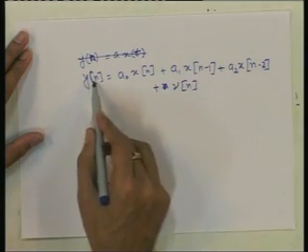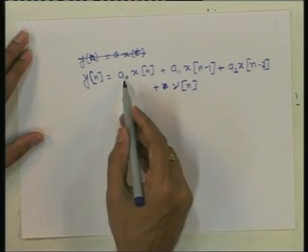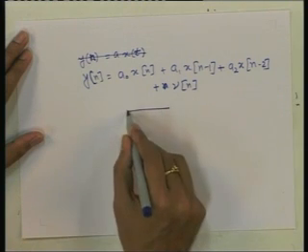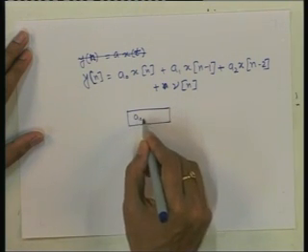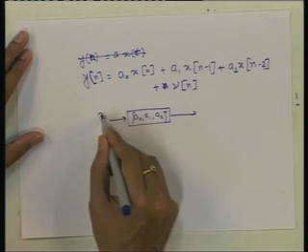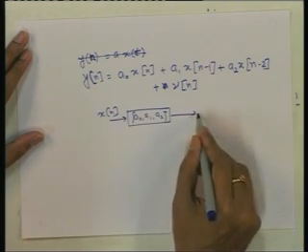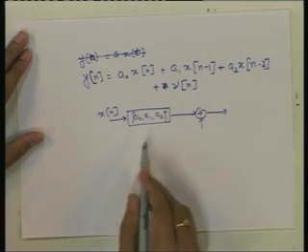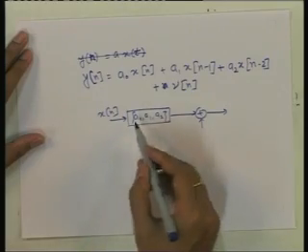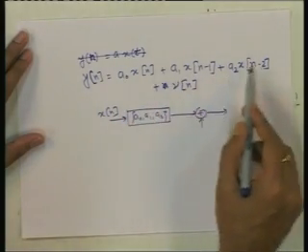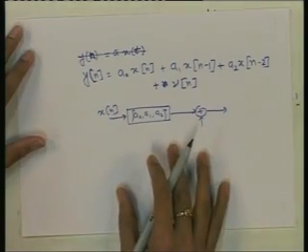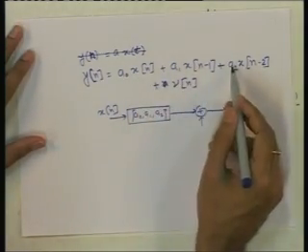Then it is like this signal is going through a filter. So, this is basically a filter with impulse response coefficients a0, a1, a2. This is the filter impulse response xn is going through. Then noise. So, multiple paths in the channel give rise to a linear filter channel here, and these filter coefficients themselves might be changing with time.